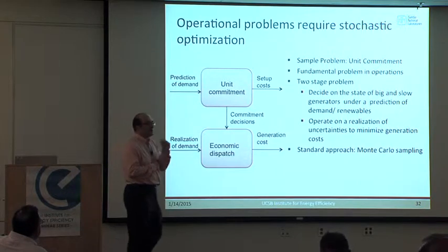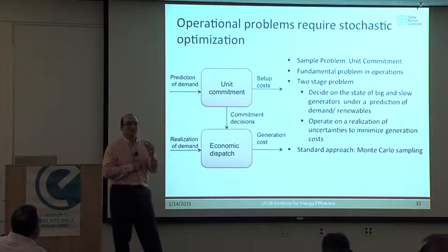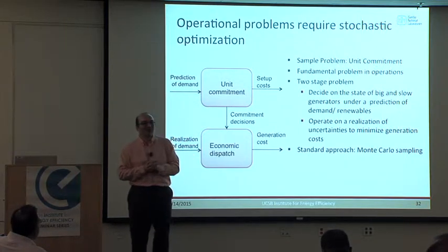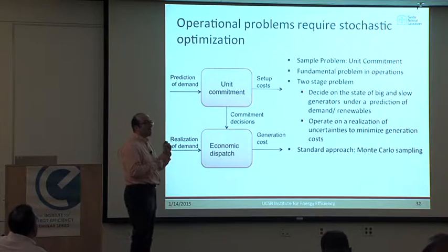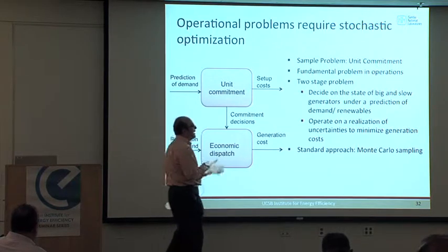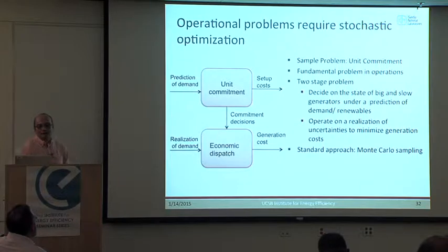But for security of the power grid, you cannot just say, I think the grid will be secure with 5% probability, and my error is plus or minus 10%. So you are looking at really low probability events anyway for security. Whenever you work with security, you want to focus on low probability events. And then using Monte Carlo sampling in that regime is not a good idea.